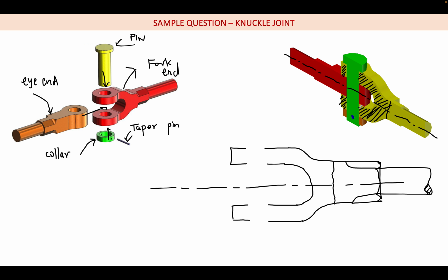So for example, if I section this also, finally what I will be having is this kind of fork, something like this, and here there will be the shaft. So I will not know whether I am having this octagonal profile itself. If the entire thing is sectioned, I will think that there is no octagon profile, only some square profile, when I see this section. So in order to differentiate that, we section only up to some portion.